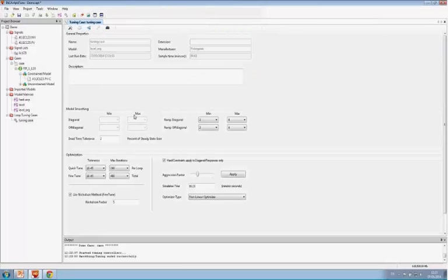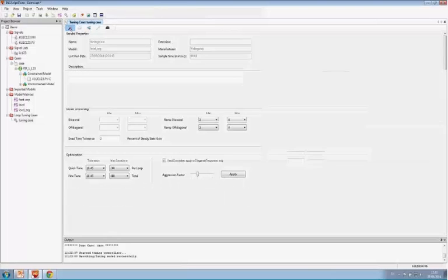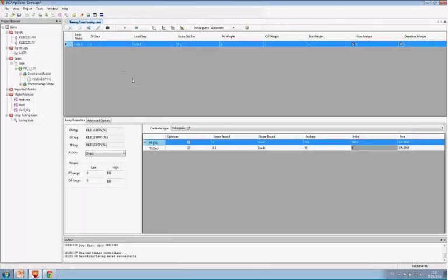I will increase the simulation time a bit to make the plots more clear, and I will uncheck this Nicholson method, which I will come back to later. Now, you can see I have still checked here the gain margin and the dead time margin, which are my stability constraints, and I will run this controller now.